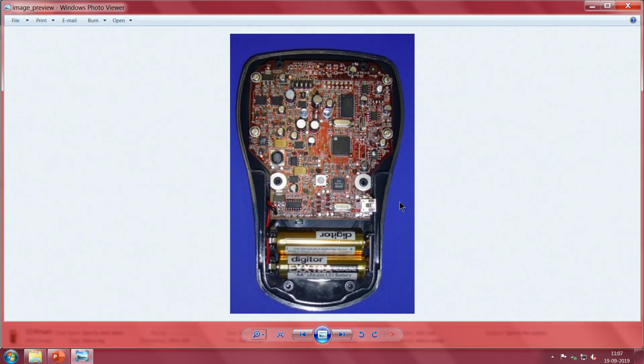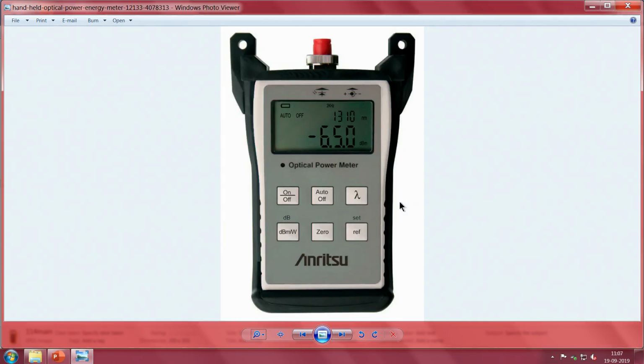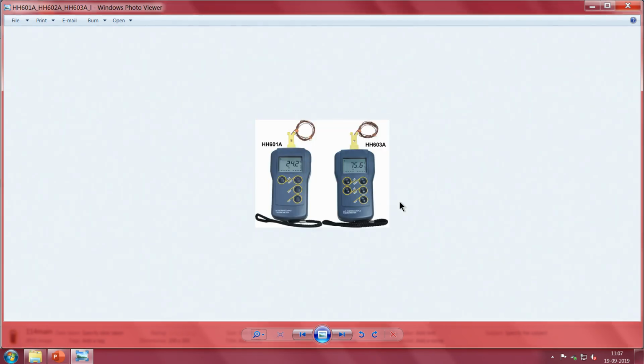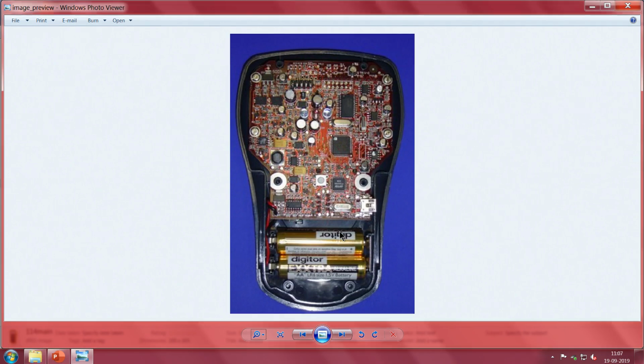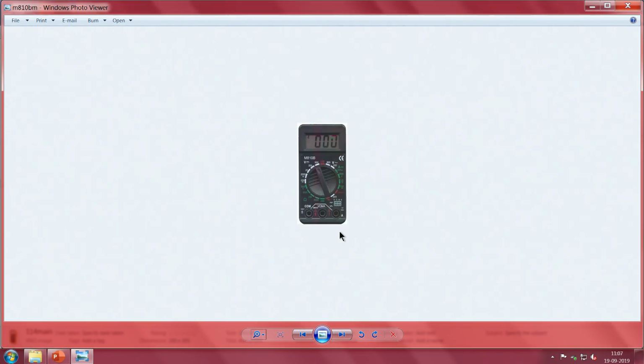But if you are to make the first prototype, what I have told you, if you are to make these prototypes, now it is possible for you to make them fit, saying I have these dimensions. So, as I said, when I said iterative, you probably must start with a rectangular PWB by which you have a schematic, you have a schematic capture, then you have a rat's nest, then you have some layout and all that. At that stage, you can import the first draft what you have made by way of a DXF file into most of the schematic capture or layout software and get this going.